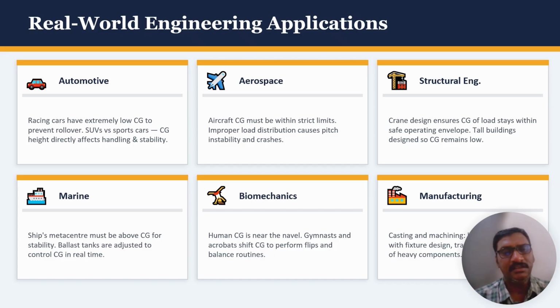In structural engineering, the center of gravity of the cross section is very important for calculating the bending stresses, shear flows and deflections. Wherever the beam is loaded, it bends about its central axis, the axis passing through the centroid of its cross section. The distance from the centroid to the extreme fiber determines the maximum bending stress.